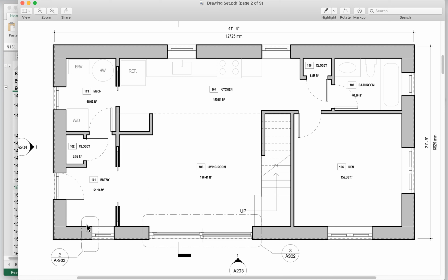We're not going to enter window installs in this portion of the PHPP. We're going to come back and talk about windows a lot in the next series, and we'll talk about how we enter window psi install information then. So we don't enter windows in this part of the PHPP. This part of the PHPP is just for those non-repeating construction or geometric thermal bridges, things like corners and the like. Okay, so we've got our outside corners. That's going to be 1.